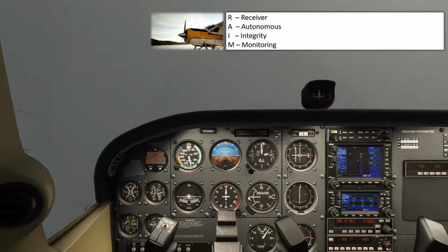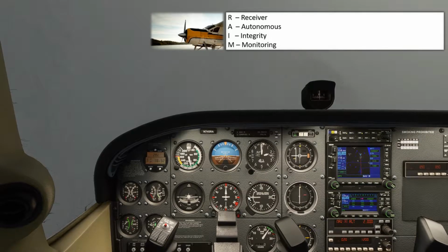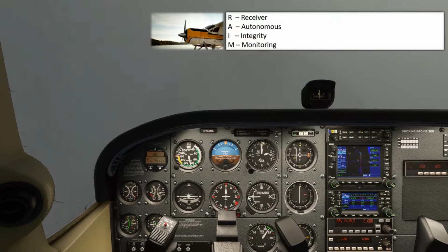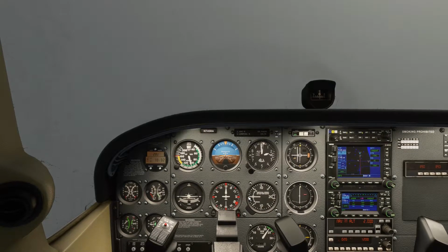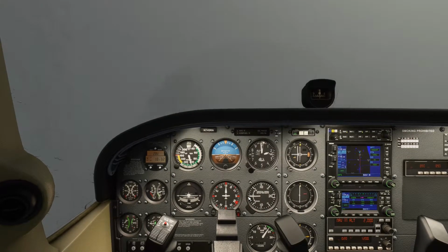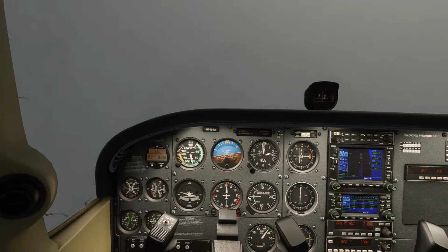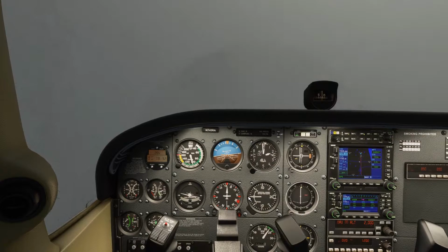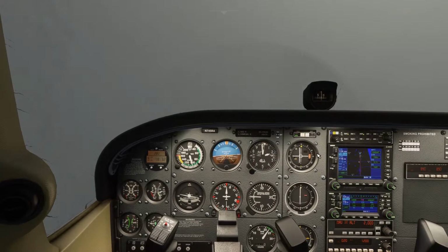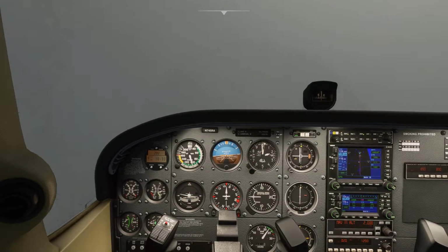position's correct. Ideally though, you want at least 6 satellites, because then what you can do is cross-check between several satellites, and it can discount any satellites that it feels that it's getting erroneous information from. So that's just a quick rundown on how RAIM works. Unfortunately I can't show you how to check it because the simulator GPS doesn't have the functionality. But that is something to be aware of if you were shooting one of these in real life.